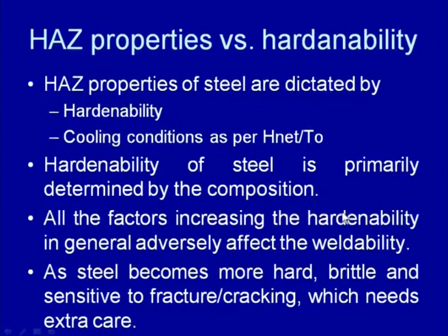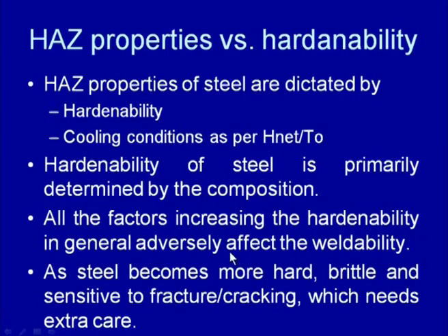So, the steel composition will basically affect its hardenability, and all the factors which increase the hardenability will make the steel heat affected zone brittle, of higher hardness and lower toughness, so that it will adversely affect the weldability.